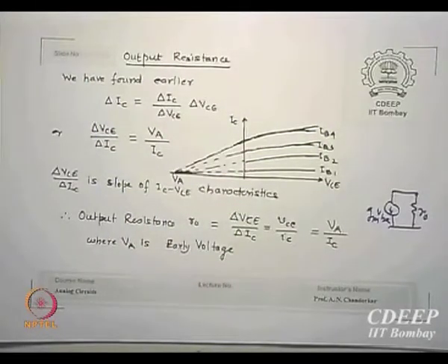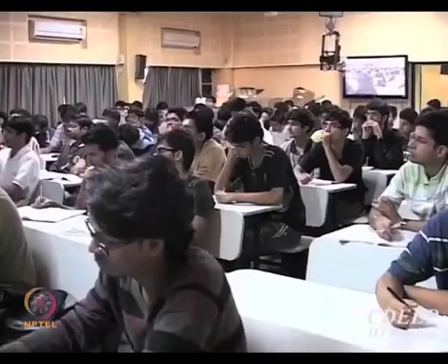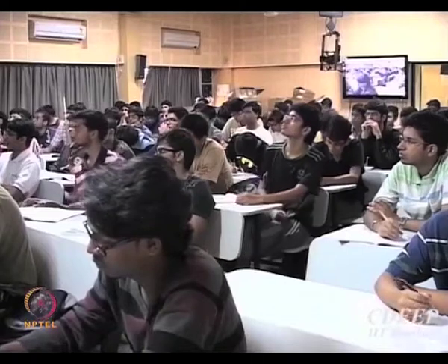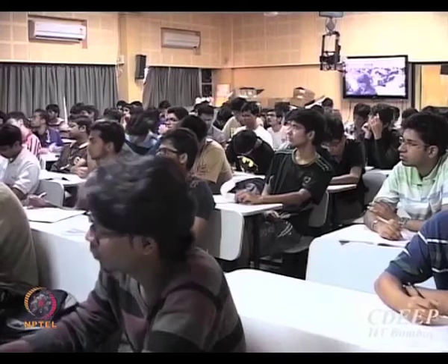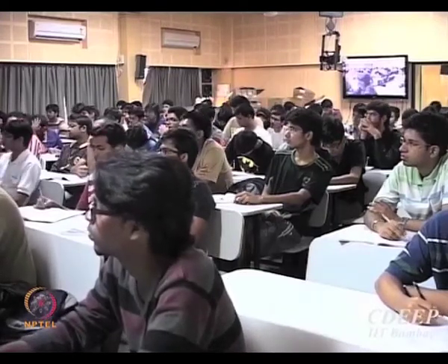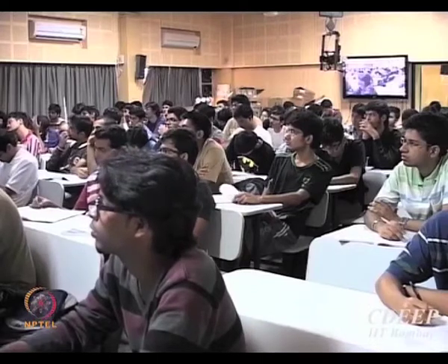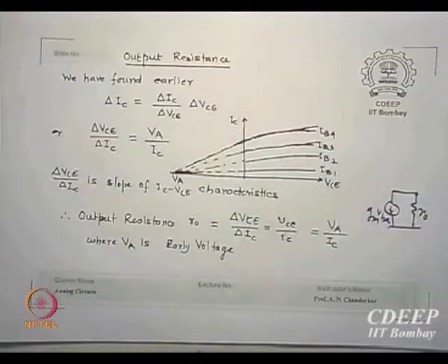Is that point clear? So if I specify to you the early voltage, 20 volt, 50 volt, and I am saying I am biasing at this bias current of IC, what am I giving you? R0 value. Is that clear? If I am specifying early voltage, this is 50 volt. Transistor has an early voltage of 50 volt. Okay. And if I say I am biasing at 1 milliamp, so कितना R0 बोला? 50 by 1 milliamp, 50 kilo ohms. So as soon as I know my bias current, I am actually telling what is R0 I am using.